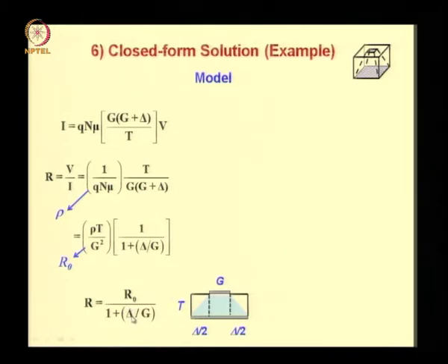Delta is the extension of the bottom contact from the top contact. So when the extension is 0, the resistance is equal to the one dimensional value, otherwise it falls as reciprocal of 1 plus the extension by the size of the top contact. Now you can easily see that you would prefer this form of the model to the form written here.